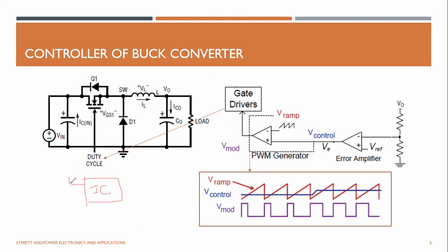It takes a power supply to power up, and from any Arduino or any kind of microcontroller, a signal can be driven to the gate driver, and the gate driver will then drive this MOSFET. The thing is, Arduinos and such can only provide 40 milliamps of output current, which is very low.